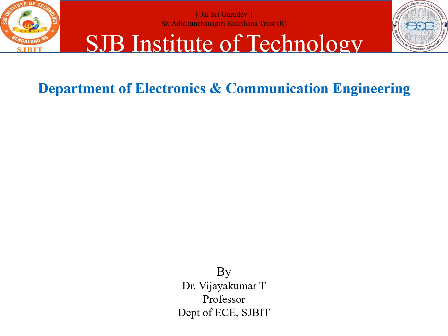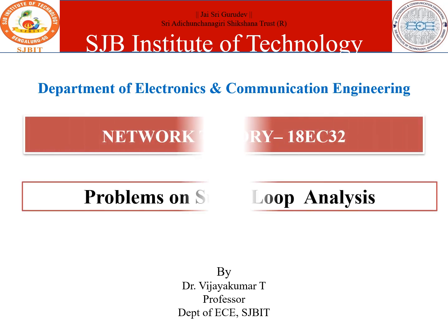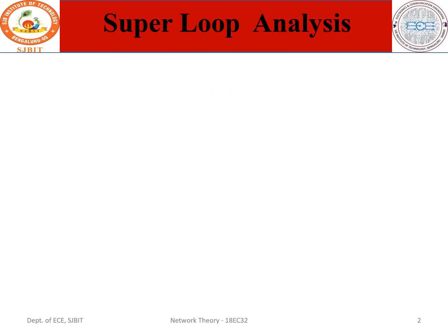Today I'm going to explain problems on super loop analysis. As you're already familiar, what is a super loop? When a current source exists between two loops, it is called a super loop. So note down the problem.